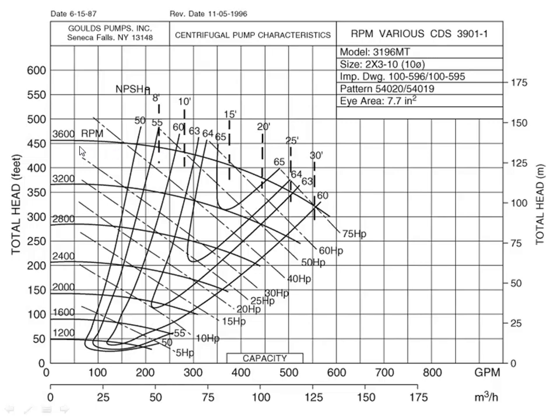The typical characteristic curve that we looked at in class previously had a certain cutoff head, and that's the amount of head that the pump can generate at zero flow rate. You'll notice that for this particular pump, they've provided different curves for different rotational rates. If you drive this pump with a motor that's rotating at 3,200 RPM, you can see what the pump curve is, 2,800 RPM, and so on.